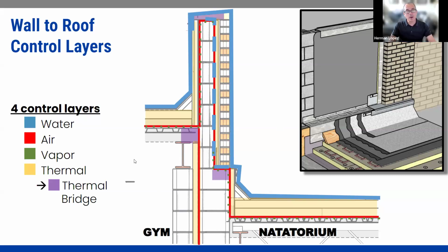Yeah, I think sometimes in our effort to keep moisture vapor out, we end up trapping some moisture in. Somebody I showed the slide to said, but if you do all of your work and you put a vapor barrier on both sides, you've kept all the moisture vapor out, not realizing there is some inherent moisture that's going to be there. Yeah, and the pool is not helping your case any. Yeah, the pool is a constant source of problems. Like, if you have a breach maybe in the paint on the inside of this wall, how are you managing that breach risk? And it's got to have a place to go.